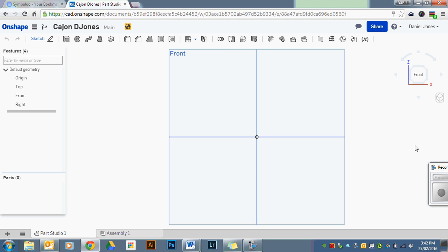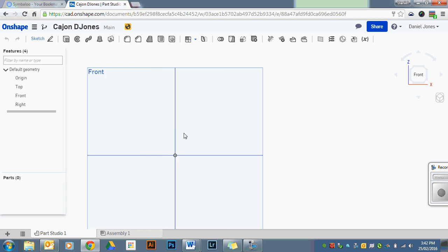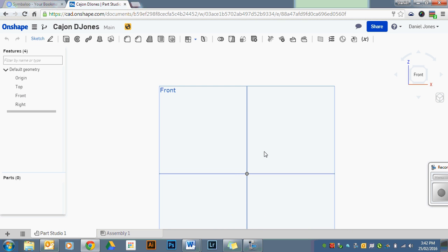In the middle of that mouse, in between those left and right click buttons, is a little wheel, a click wheel. If you hold down that click wheel, it lets you move the work plane around all over the place, which lets you drag to different parts of the drawing, because your drawing is going to be bigger than what's just here. So for that reason alone, you need to use a mouse with a click wheel. You can also use that click wheel to zoom.